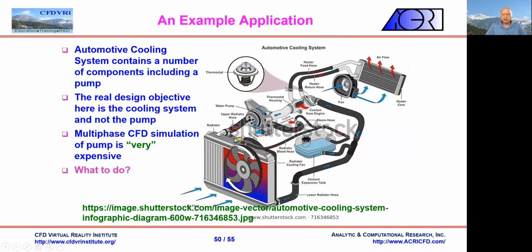Look at this automotive cooling system. It's got many components. As you can see, there are pipes, there is a pump, there is a fan, there is electronics, there is a radiator, all things are going on. So what is commonly found is that the design and simulation of the pump consume a disproportionately large amount of time, which I'll get into in the next slide. Our real objective here is to design the cooling system, not the pump, okay? So multi-phase CFD simulation of the pump is very expensive. So what do we do?